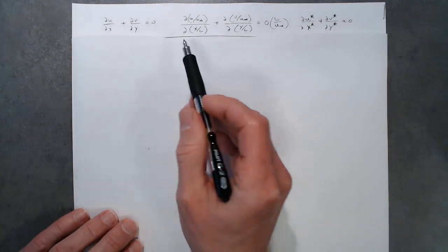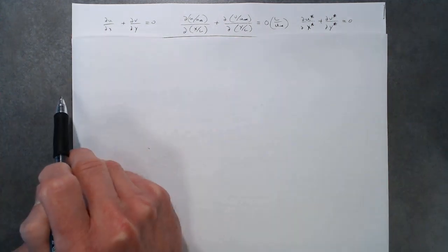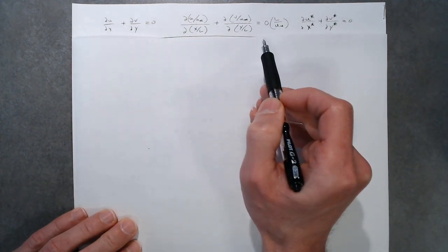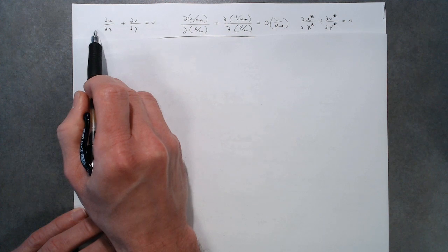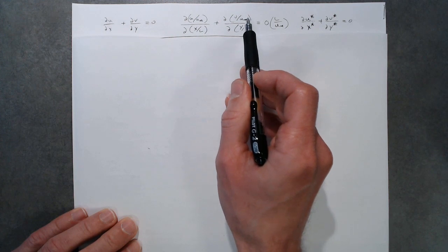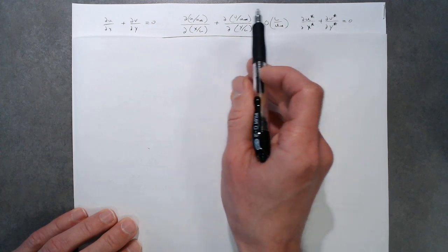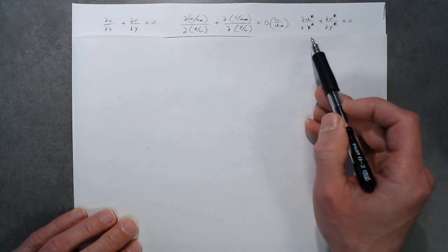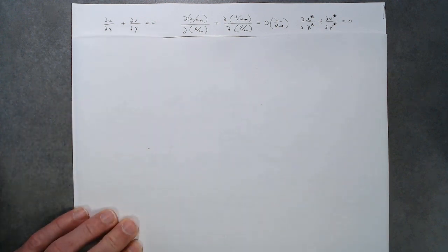And so we see we can express this in terms of our normalized or non-dimensionalized variables, essentially by multiplying both sides by L over u infinity. Again, if I considered this equation and multiplied by L over u infinity, then I can distribute 1 over u infinity into the numerator and 1 over L into the denominator, and arrive at this equation. Well, of course, this side remains 0, and we can simply write the conservation of volume in non-dimensional form this way. So it looks essentially the same as it did in our dimensional case.